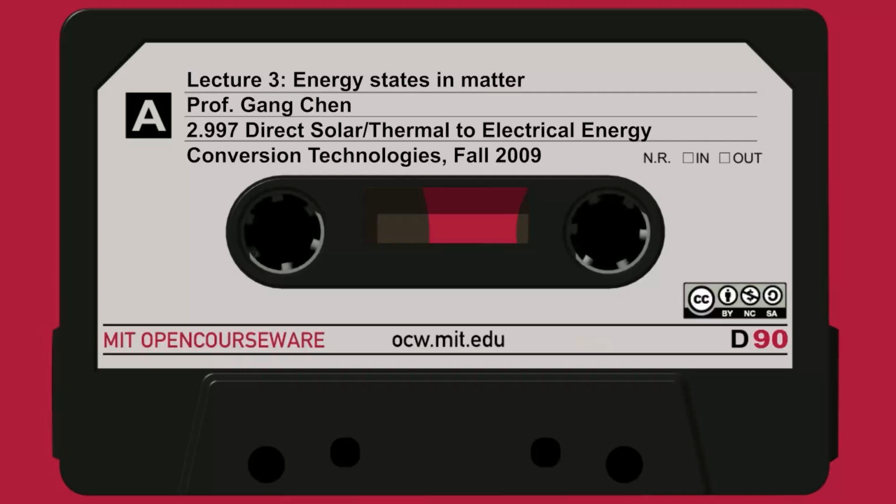This is very relevant when you think about what material you want to choose for thermoelectrics. Typically, the larger the spring constant between the atoms, the higher the frequency, and the stronger the bonding of the atoms. And this will lead to high thermal conductivity.